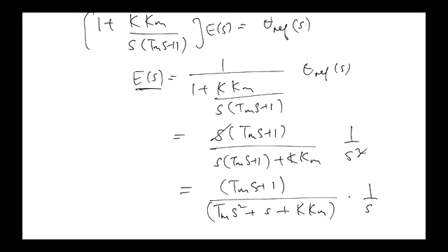The thing on the bottom is a quadratic, and all the coefficients are positive. So the roots of that polynomial will be in the left half plane. The poles are in the left half plane. So it's a stable transfer function. The step response of a stable transfer function is a step out in steady state. Okay, so the error goes to a constant value.